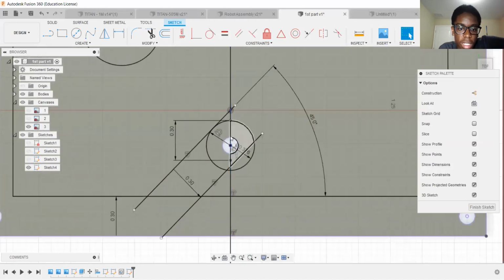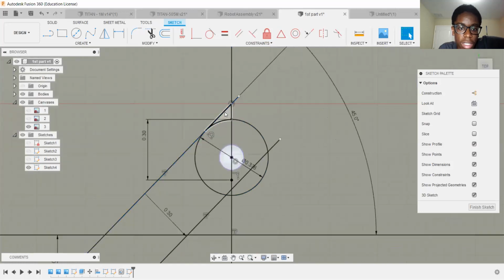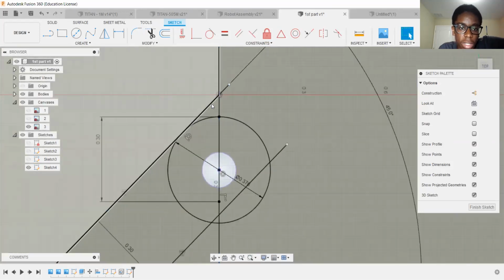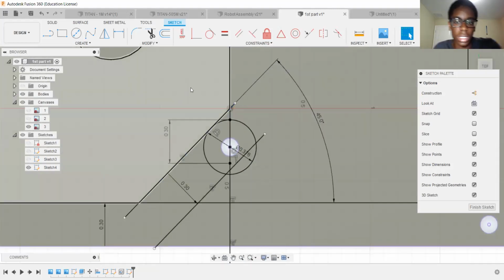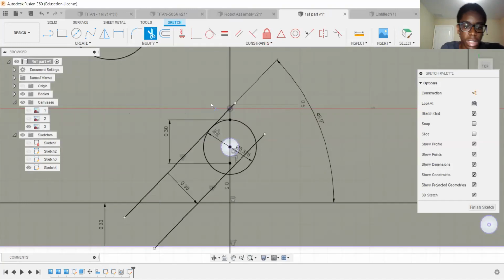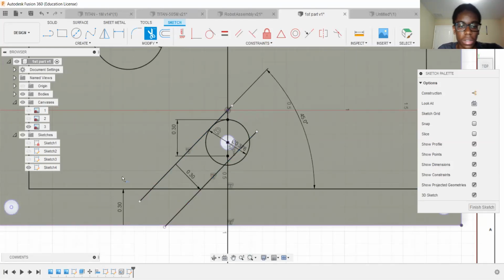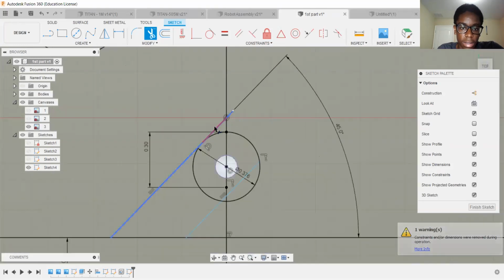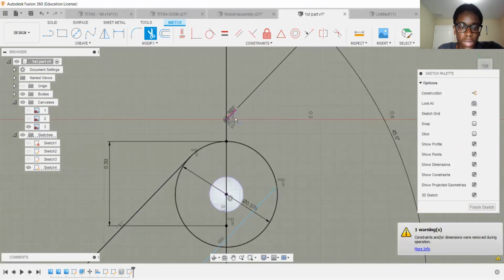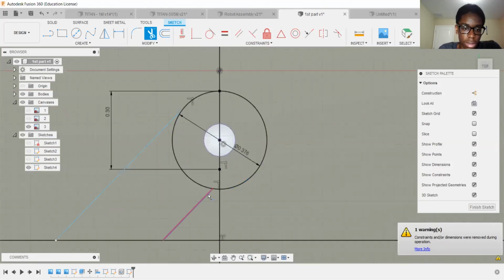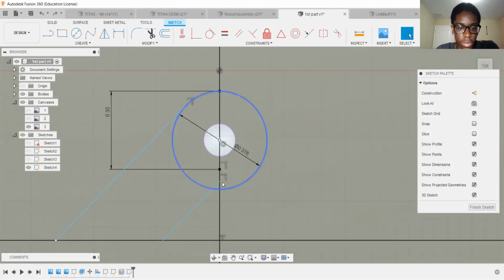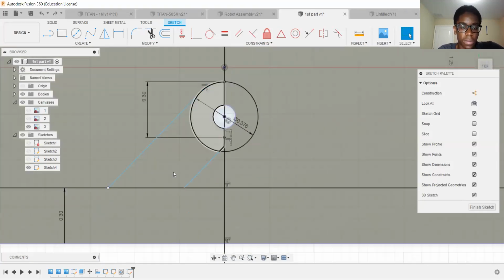So we have most of our lines, but it is kind of giving us a couple of lines that we don't want. So like this line, and we don't want those if we're going to mirror. So what we could do, and this is kind of optional, is go up here to modify, and under modify we have trim, or T, and we could just take away those edges that we don't want. So like this edge, we don't want that, that. And it doesn't matter if it turns blue since we already offset it. So all those edges, actually not that one. So we want this edge. So we just want these two.